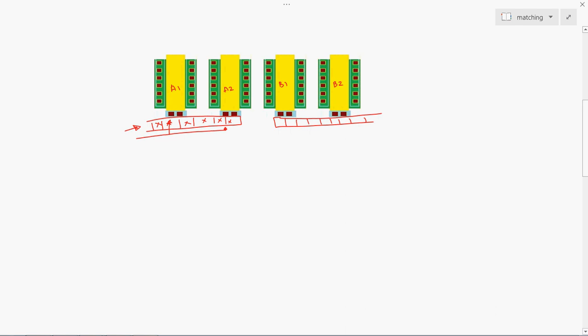And one more thing, it is not only routing related issues; it is also associated with etching related issues in each individual transistor. As I said in my first video, if the 4 transistors are fabricated at the same time, in the same foundry, with the same technique, the etching will not be uniform; it will differ from transistor to transistor. Due to etching the transistor performance and VT may vary, and due to routing the performance may also vary. So many things are associated with turning the transistor on and off, or with delay, not only routing, not only doping, and not only ion implantation. It is all related to the fabrication process.